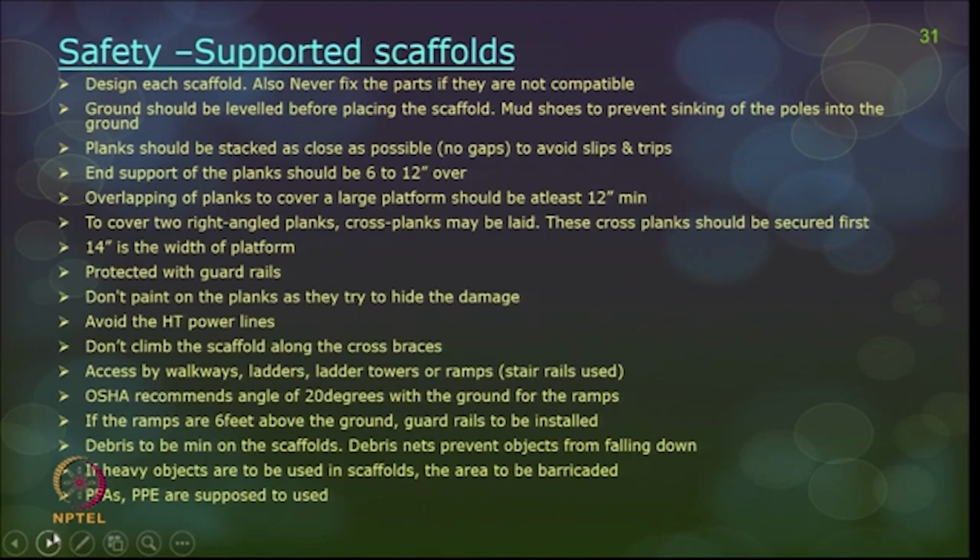If heavy objects are to be used on scaffolds, the area should be barricaded, and personal fall arrest systems and proper PPE are supposed to be used for the workers who work on the scaffolds, and also for any workers and supervisors who visit the site and do the inspections. For all, it is recommended, okay.